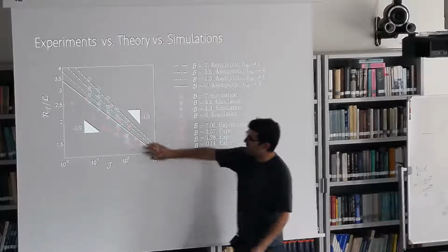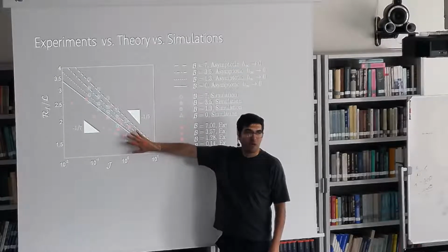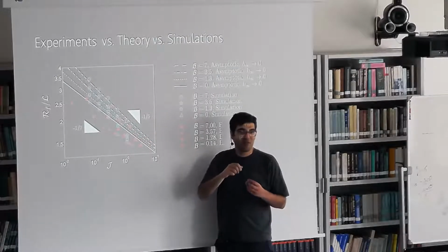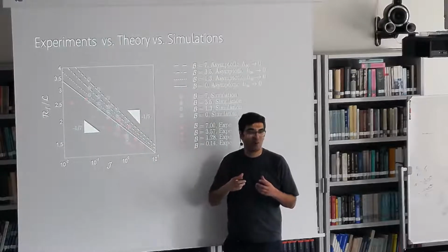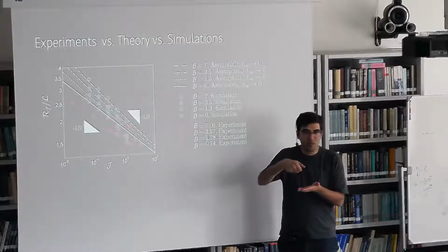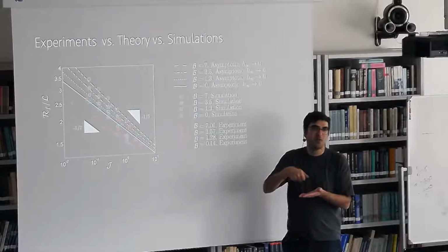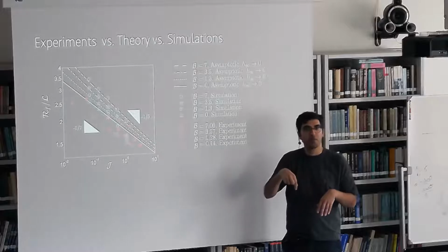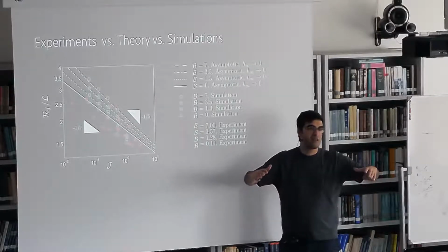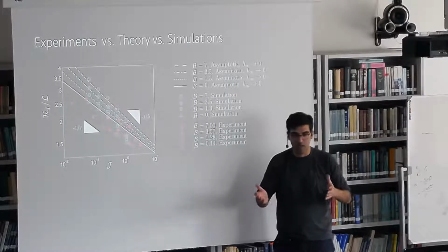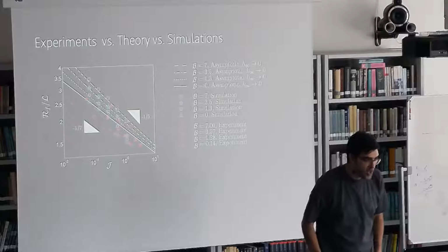So you might ask what's happening here when everything doesn't compare. You should remember that these are very large plastocapillary numbers, where yield stress is dominant. So you can think of it like if you want to deposit a droplet of toothpaste, it heavily depends on how you do it. So it's memory dependent. The method of deposition matters a lot. So the solution that you get in experiments, for instance, is not unique anymore. So that's what's happening there. How much time do I have?